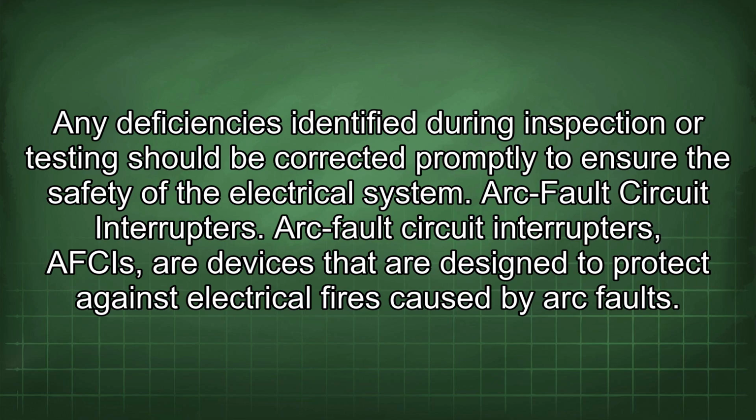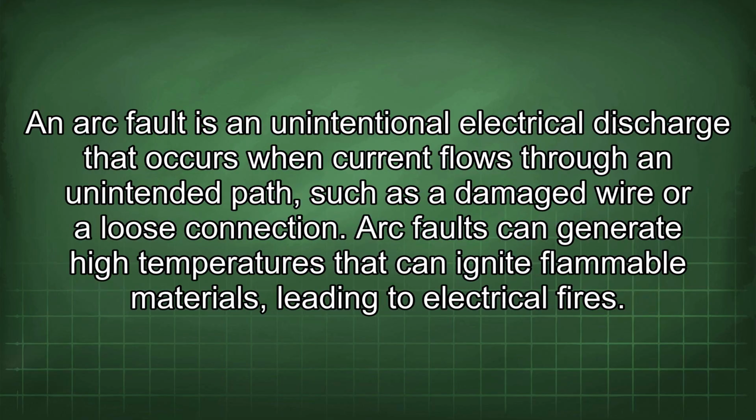Arc fault circuit interrupters. Arc fault circuit interrupters, AFCIs, are devices that are designed to protect against electrical fires caused by arc faults. An arc fault is an unintentional electrical discharge that occurs when current flows through an unintended path, such as a damaged wire or a loose connection. Arc faults can generate high temperatures that can ignite flammable materials, leading to electrical fires.